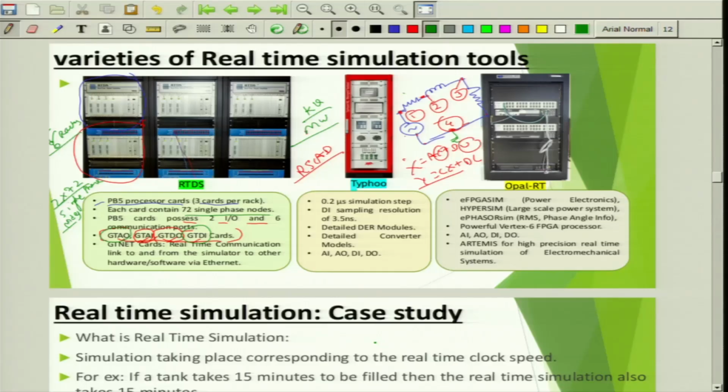So what you do is, using GTAO ports, of course these voltage signals will be in the range of 0 to 5 volts. They're low voltage control signals basically, right? Now what you can do is, you have the voltage source model within the RTDS platform, then you can use these GTAO blocks, and then you pass this control signal to the grid source or grid emulator, so that you can generate the voltage varying from 0 to 400 volts, and you can carry out multiple actions. So GTAO has such kind of application. I will discuss in detail also when I go to power hardware in loop experimentation.